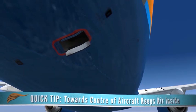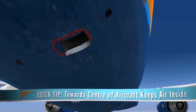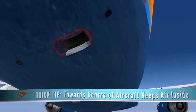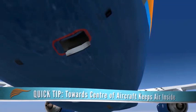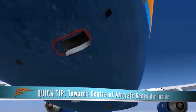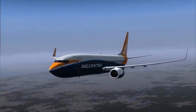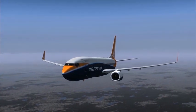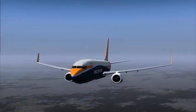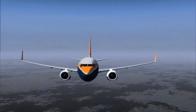A good way of remembering how to operate the outflow valve switch when pressure is manually controlled is moving the switch towards the center of the aircraft keeps the air inside. The full range of motion of the outflow valve takes around 20 seconds. To make things slightly easier when manual operation is in place, there's a placard in the cabin pressurization panel that shows the standard settings for cabin altitude versus cruising level.